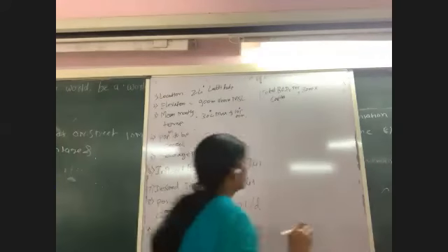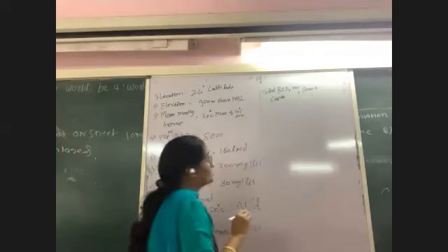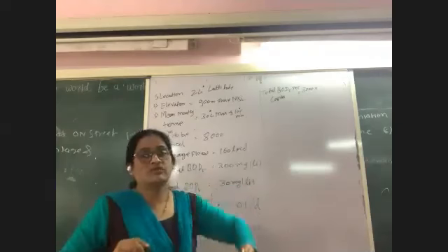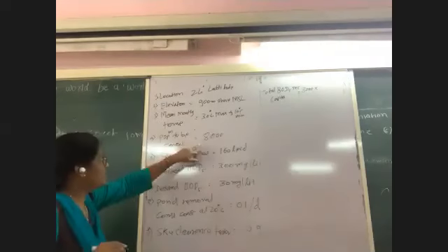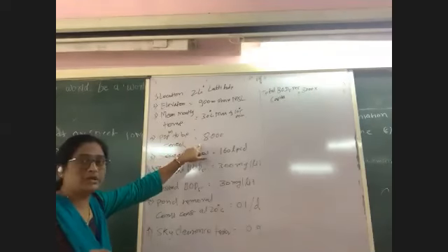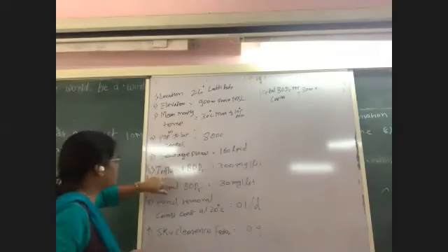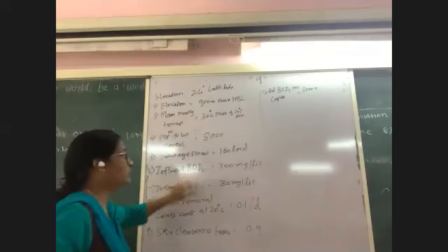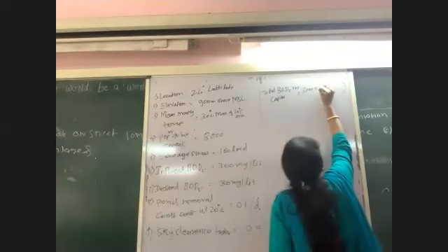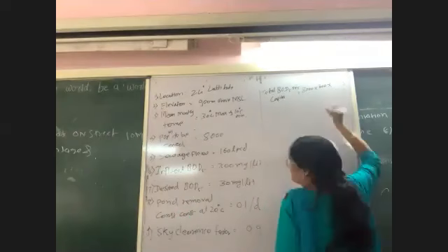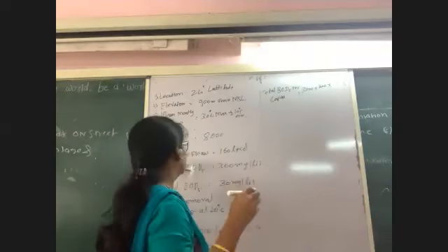So first of all, you need to calculate the total BOD per capita. For that purpose, population data is given to you. The population of that particular village is 8,000. Then what else data you have? Influent BOD. It is 300 milligram per liter. And next is given to you sewage flow.